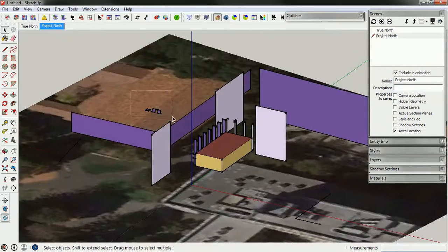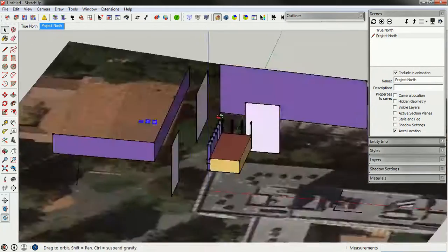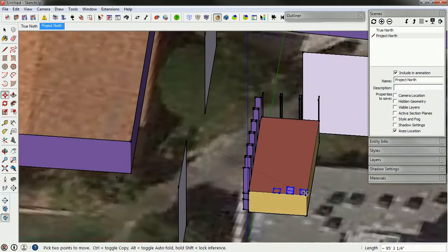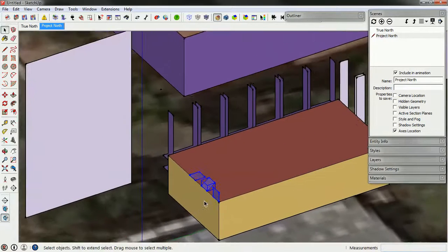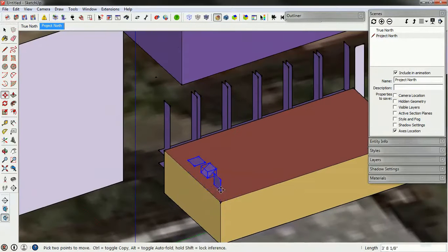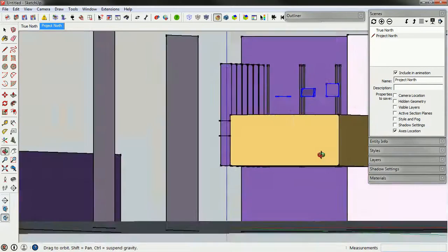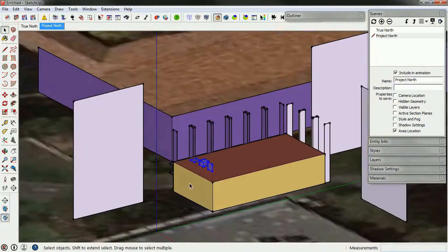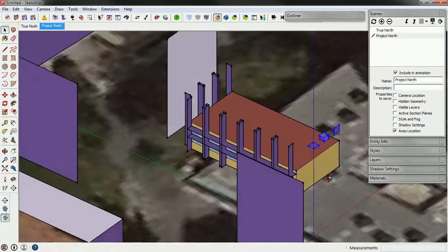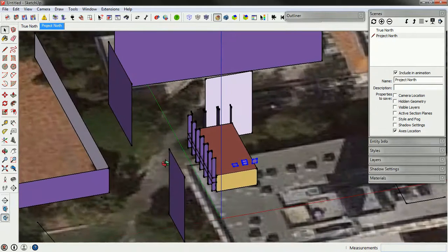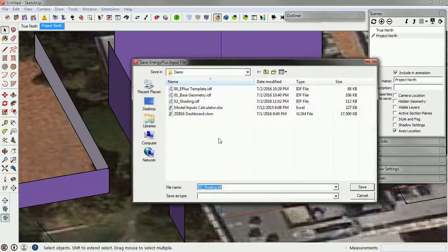Finally, notice again these PVs that are floating above here. I'm just going to tuck them in next to the building, or on top of the building here. And we're going to talk about these more in a few weeks. Make sure that they don't intersect with the building geometry, but that they're above the building geometry and kind of out of the way. We'll come back to them. Please do not erase them. And actually, this is a good time. I'm going to save this again. 03